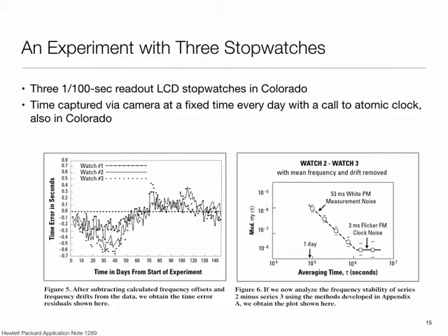Okay, so what you're basically saying is, I have a clock frequency, and I'm going to figure out by how many ticks the counter would advance, and then arrange for the counter to generate an interrupt when it reaches that value. And you'll have to deal with some nitty-gritties, like your counter may have a rollover period which is smaller than this, so you'll probably count how many times it has rolled over, and then the remaining delta. Okay, so a reasonable strategy.